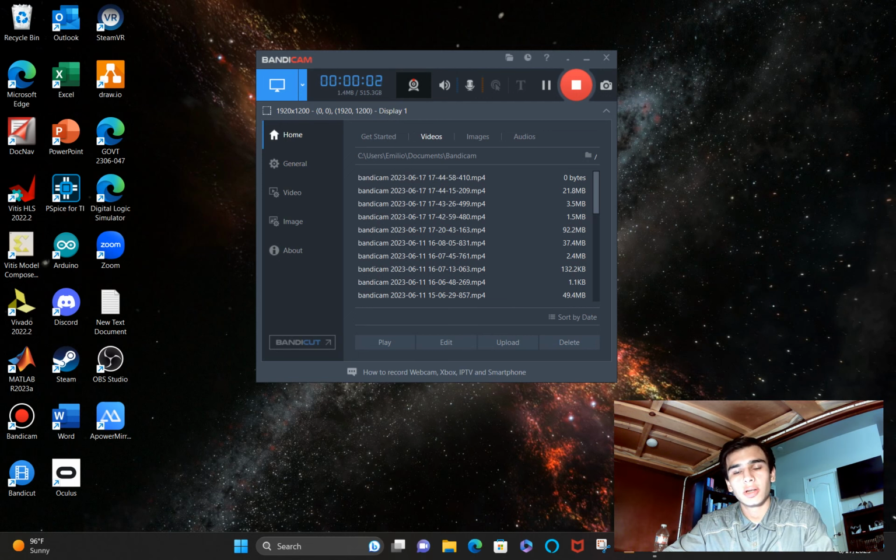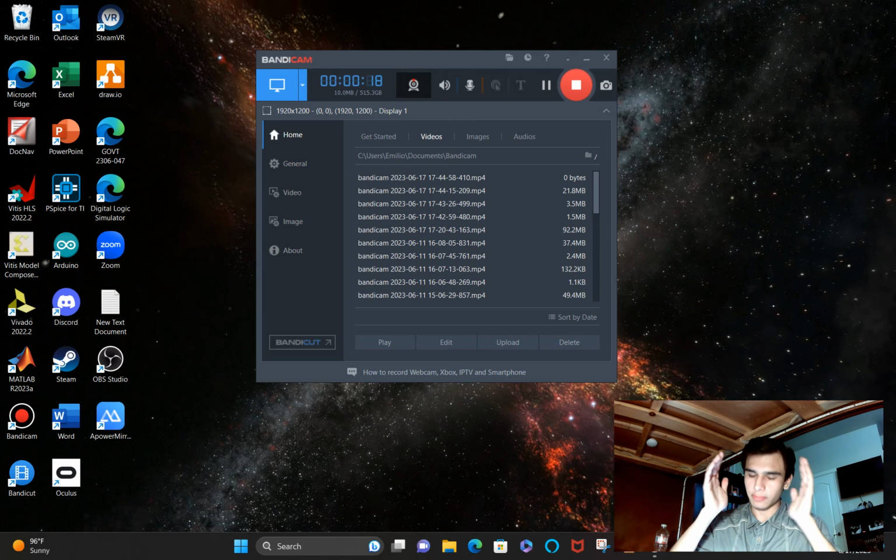Hello everyone. So for this video, we're going to go over everything you need to know for lab 2, and in that lab you're going to be making a multiplexer. You're going to be combining a bunch of little multiplexers to make one big multiplexer, and that's one way of doing it. There's another way of doing it with combinational logic. So we're going to review that.